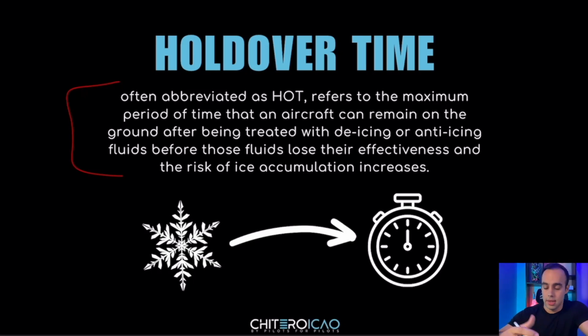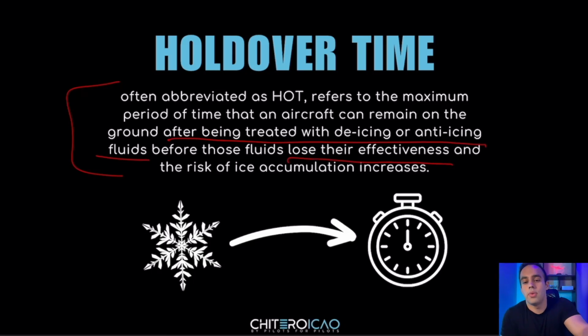So basically we have holdover time, often abbreviated as HOT, and it refers to the maximum period of time that an aircraft can remain on the ground after being treated with de-icing or anti-icing fluids before those fluids lose their effectiveness and the risk of ice accumulation increases.